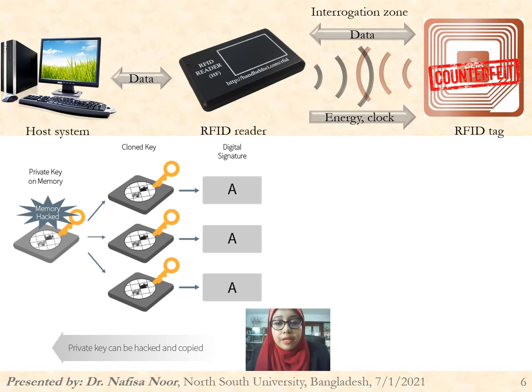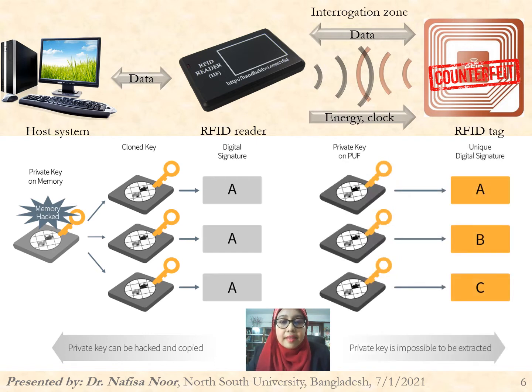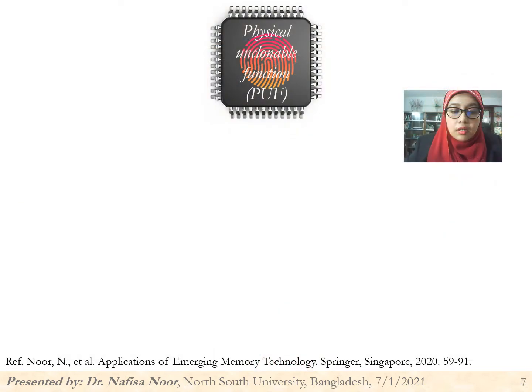So for hardware security, we need to rely on processes that are inherently unclonable. So if the attacker has full possession of the device and tries to look into the device through advanced reverse engineering tools and attempts to fabricate a similar chip, the attacker should always fail to produce a clone. And these devices themselves should be generated with such random features that even the manufacturer cannot produce a clone. The physical unclonable functions or PUFs can meet that security requirement.